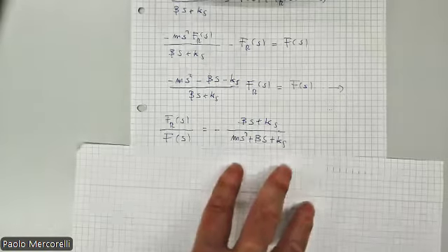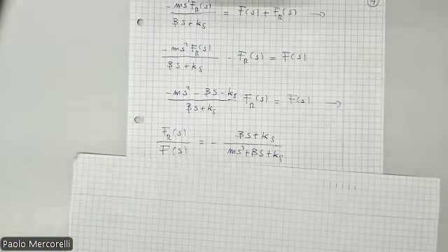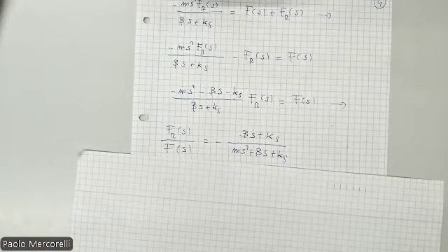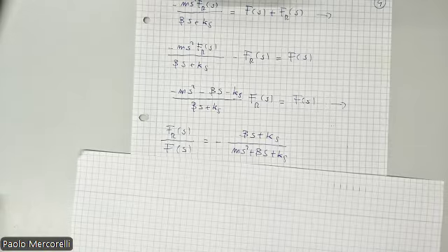Is it okay here? Very important: the denominator in the transfer function does not change, it is always the same. Of course, if I consider a different input, this means a different model, because you remember that in dynamical systems, before modeling, we orient the system. We define the input and we define the output. The output can change, and the input can also change, but if you change the input, you change the model structurally.